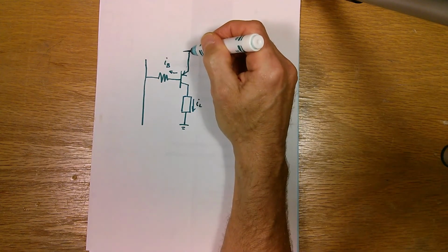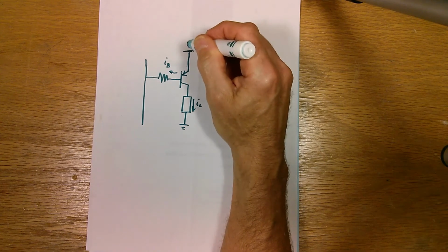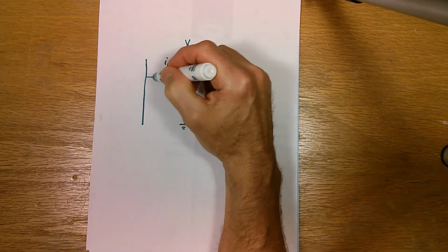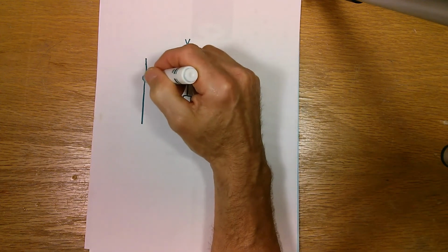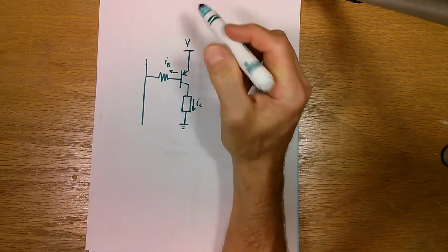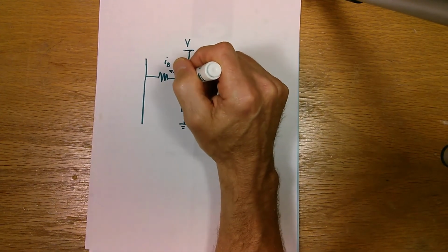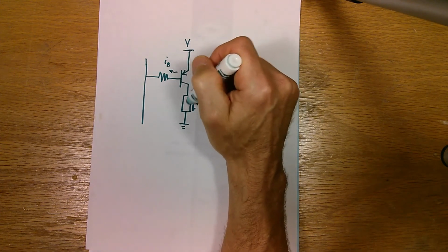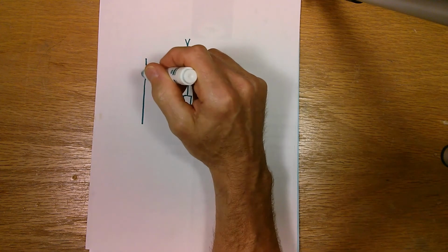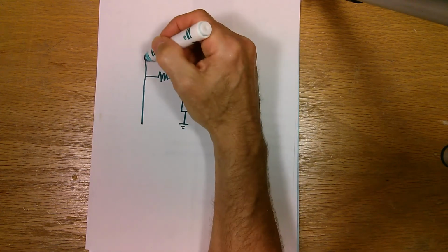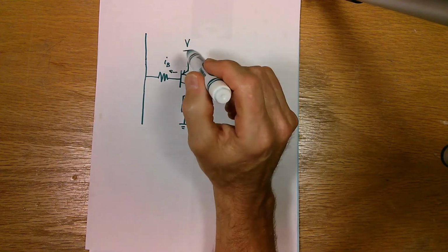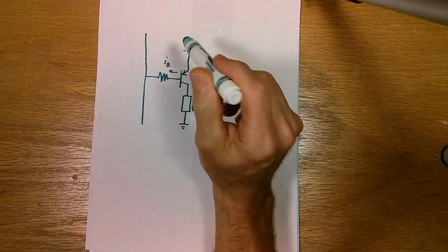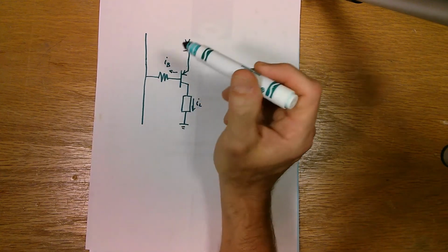And so in this case, I'm not going to be able to switch something that's at 12 volts here, because when I put this to 5 volts, we still have a voltage drop across this resistor, and you'll still get current flowing through here, and the transistor will be turned on. So this is the only caveat with using a PNP transistor and switching this load. The voltage that you're driving this load from has to be the same as the switched voltage on the microcontroller. I can show you, using a couple of transistors, another circuit that allows you to switch with 5 volts and switch a much higher voltage. We'll get into that in a minute here.